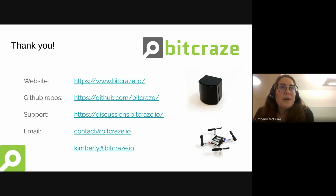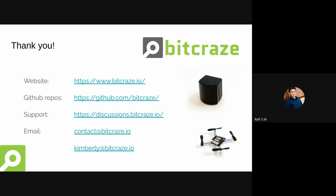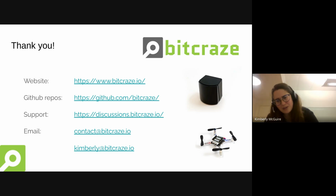On the hardware itself, this was just me giving a position set point, as I showed, so that didn't have any ROS included, and we have controllers on the Crazyflie firmware itself, so it was doing that all by itself. The Crazyswarm 1 and 2 projects do more with trajectory control, so I hope to present it at one point as well. They also do a lot with uploading the trajectory on board the Crazyflie, so that you don't have to communicate every single step along the way, because that's kind of annoying in terms of swarming. I'm not sure how far the micro-ROS people are in terms of trajectory control on board with ROS. I don't think they have something like that, but yeah.